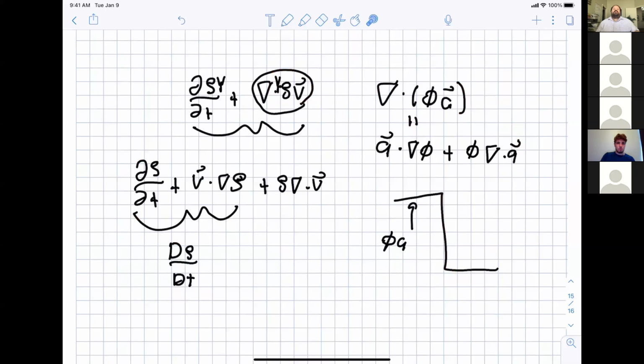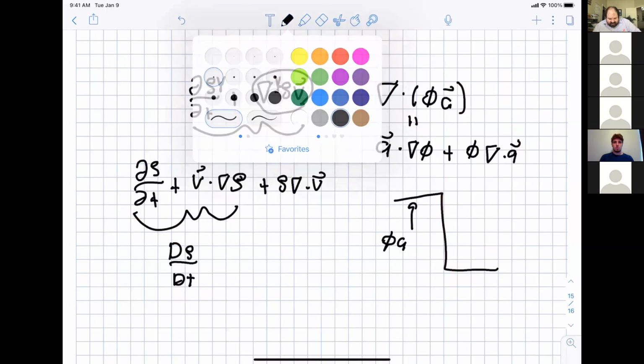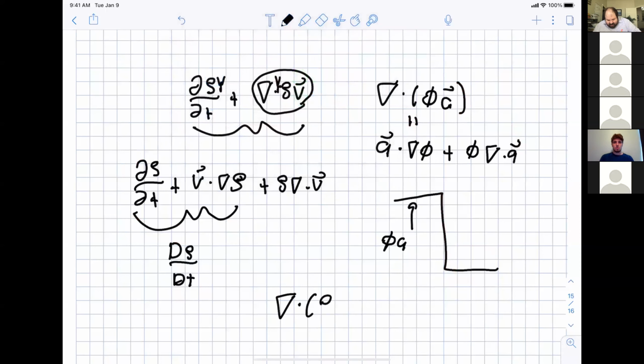And so the mass fraction itself is the only variable that is valid for this type of flow, or for these types of single phase equations. But the quantity, the divergence, even though mass fraction itself is physically okay, the quantity rho Y_i v is not okay.